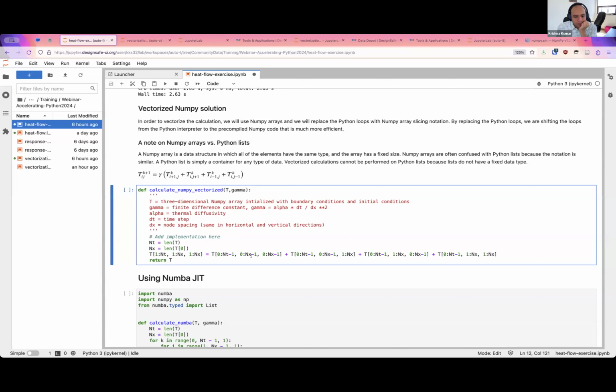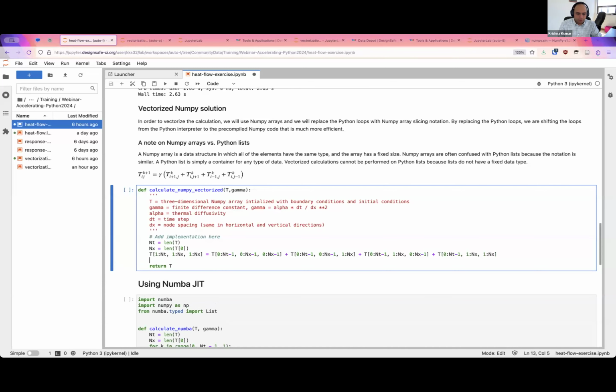This is the i j value. So we have basically written this equation as temperature at time step k plus 1. This is going to be temperature at time step k. This is i comma j. I'm going to drop the k. Then this is i comma j plus 1.